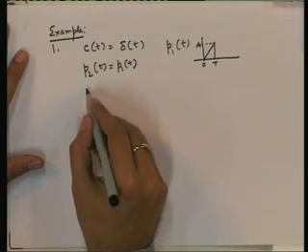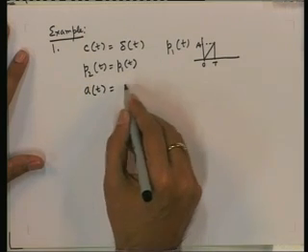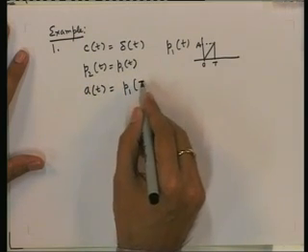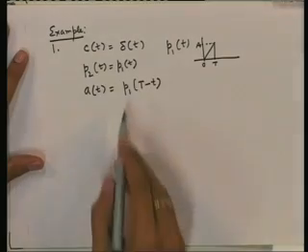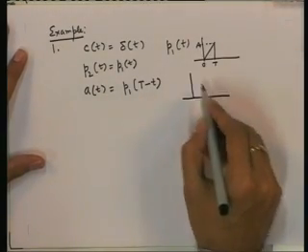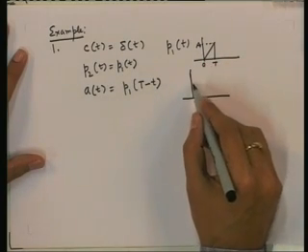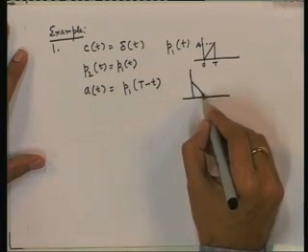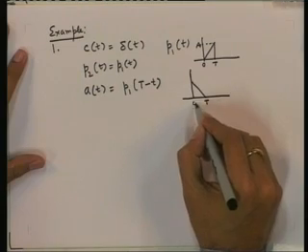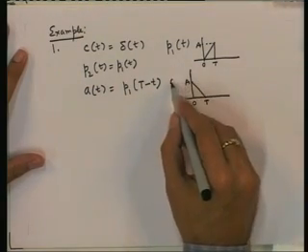Then what is the matched filter to P(t)? It is a(t) equal to P1(T minus t), where P1 is the same as P2. So, can we plot a(t)? If we plot, it will be reversed. So, T will come to 0, 0 will go to T. So, this is T, 0, A. This is our a(t).